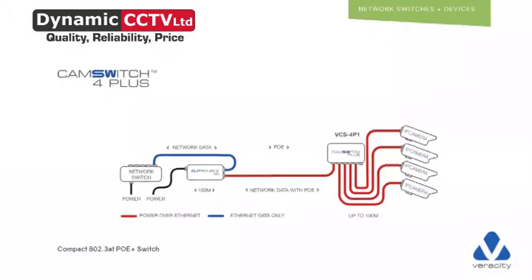So I'm going to go to the diagram. And again, I'm going to show you a way of doing this. You can still power this with a power supply if you choose to, standard Molex connectors, or you can use our outsourced 30 PoE injector to power it as well. Now, again, depending on what you're injecting it with, in this instance on the screen now, that's a 30-watt injector. That's going to run the switch and the 4 cameras.